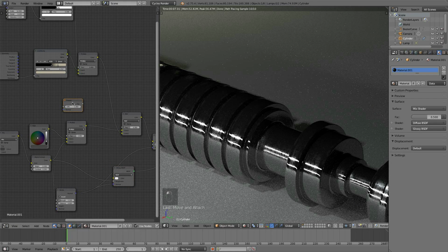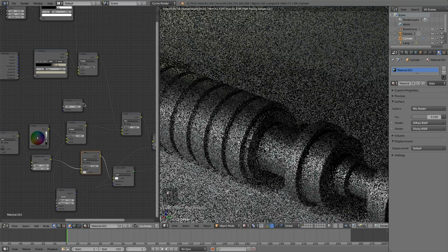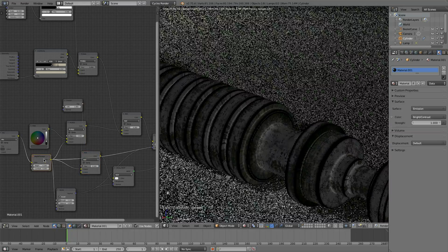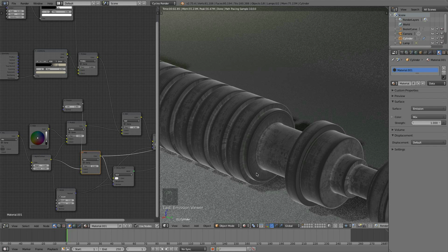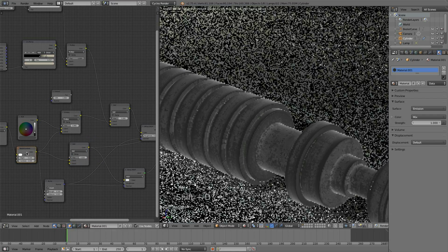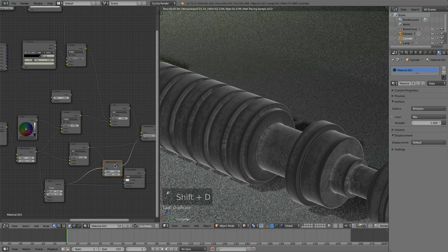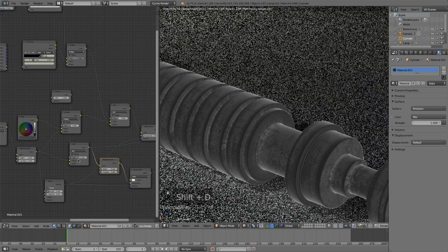And I'm going to add it to our brightness and contrast node here. So just go Color, Mix, change it to Add, and drop it into there. So now you can see before and after. We get the highlights along the edges of the mesh here, which will make the glossy look a little bit better. Cool. Now we might want to add in some more contrast to this after adding the Fresnel to it here. So we can just duplicate this bright contrast node and drop it in there again. Whoops, I dropped it in the wrong spot. Command Z. Shift D it and drop it in there.